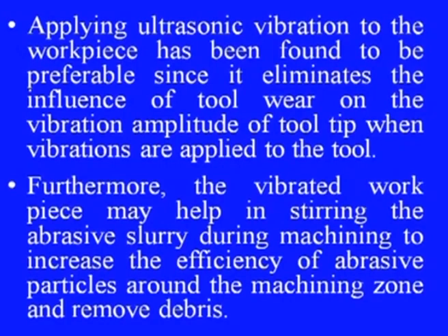Applying ultrasonic vibration to the workpiece has been found to be preferable, since it eliminates the influence of tool wear on the vibration amplitude of the tool tip when vibrations are applied to the tool. This was basically the motivation while developing the version where the ultrasonic frequency is given to the workpiece itself instead of the tool.